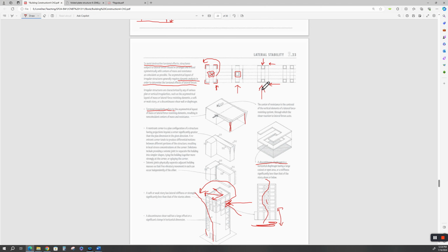So how do you think this whole thing behaves? Now, to me, this has a weak point. The weak point is what's tying these two together. If it's light structural steel framing, then you're going to have some kind of bridging in between here so they'll act in consort. If not, you run the risk of differential loading on each side of this frame.